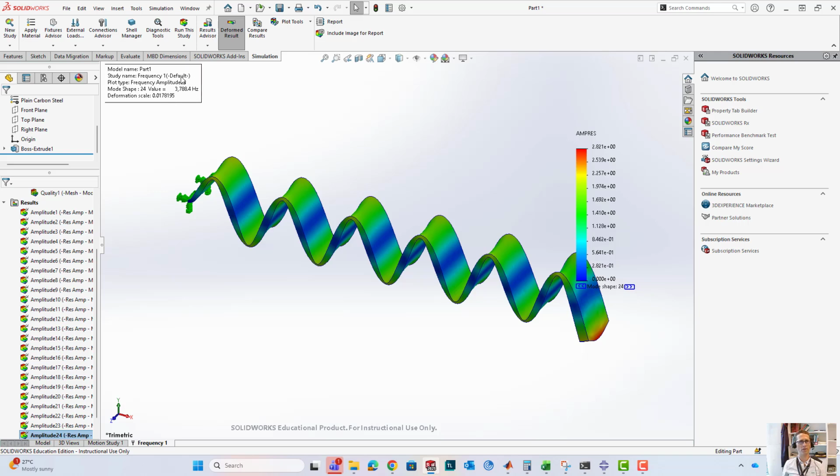Not only that, I would need to be able to excite the structure at a relatively high frequency. This is not an enormous frequency, 3.8 kilohertz. We should be able to achieve that with an excitation using a modal impact hammer or a small shaker.